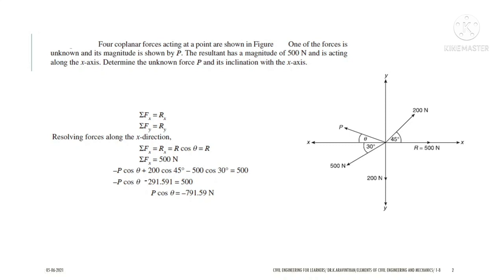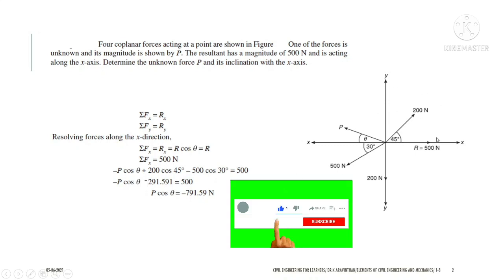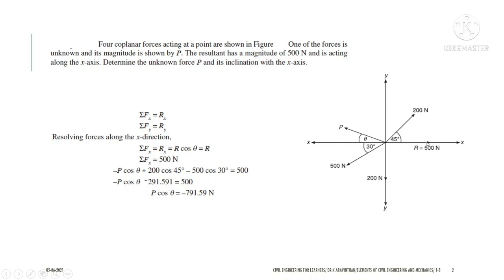If there are multiple forces, we know the concept of resolution of forces. So we will be resolving all the forces vertically and horizontally in order to find the resultant. Now let us find the sum of all the forces acting in the horizontal direction. Here we will consider all the horizontal forces with respect to the resultant. What we mean by resultant is that whatever forces are acting are made into a single force called the resultant. Now we will resolve all the forces horizontally.